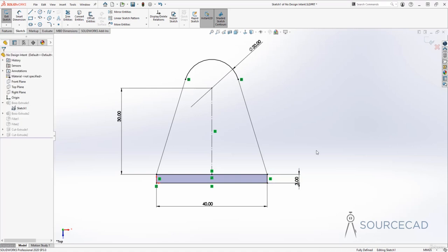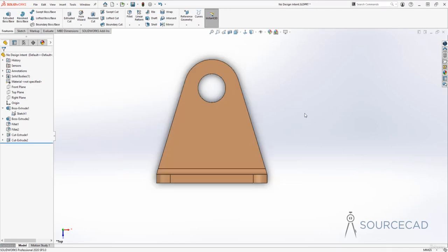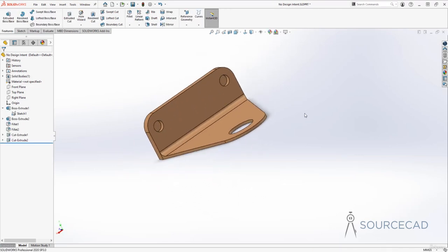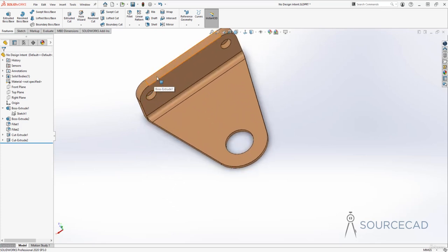So it is now changed. Now we have this thickness as 3 units. So we are done. Let's click on exit. All right. And let me orbit this drawing and you'll see this. Now we no longer have these two holes. And why is that? Well, that's because the thickness has increased and the hole depth is just 2 units. It's just 2 mm. But now this object has a total thickness of 3 units or 3 mm. And that's why we no longer have that hole.